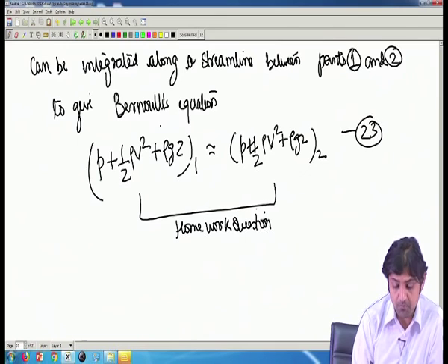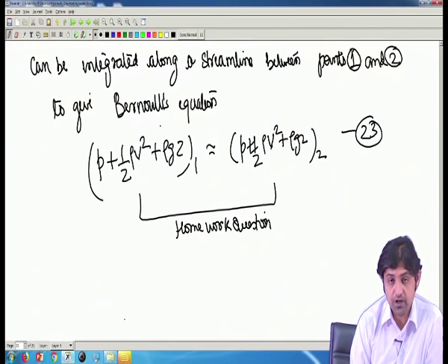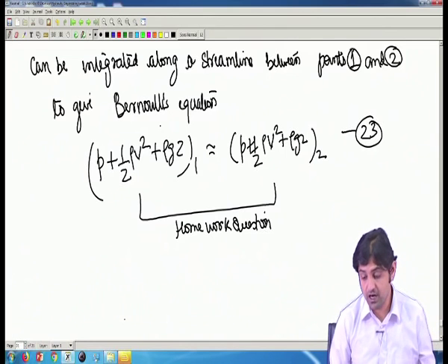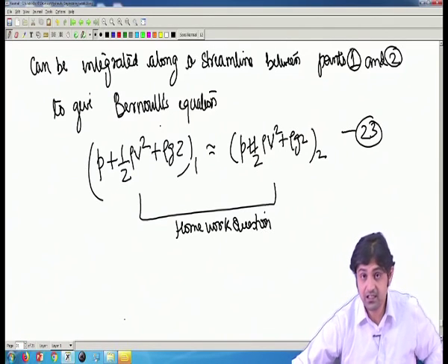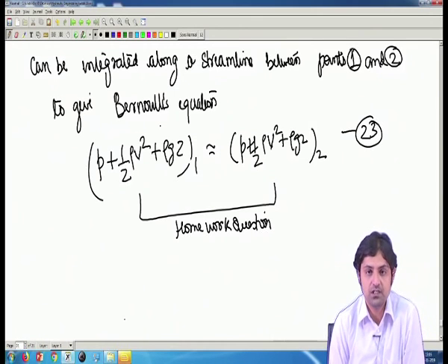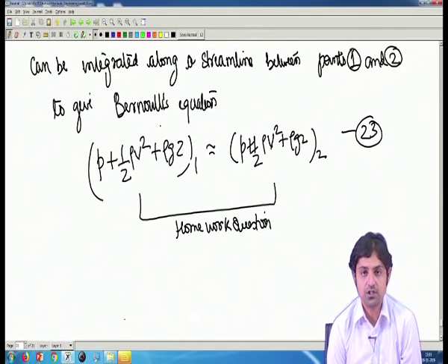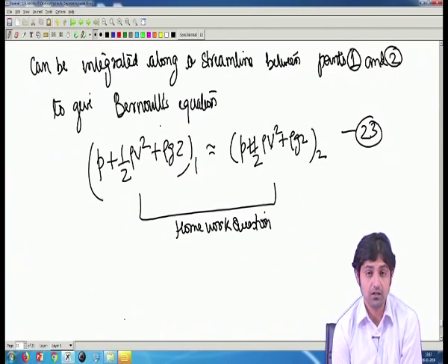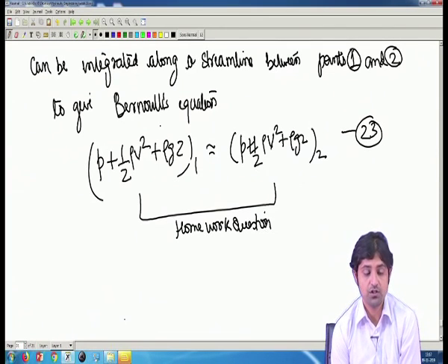So, from the beginning of this module, you have seen how we went ahead and tried, from basics, from the material derivative and the geometrical properties, to talk about the strain rates, the shear strain rates. Then we went into the equation of continuity using the material derivative, then the equation of momentum. We saw the deformation laws in fluids.